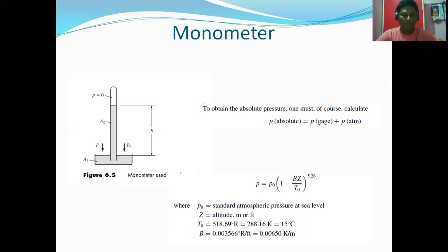So the column has a graduated scale fixed in position with the help of some instrument, set to 0 for each reading, and the level of the well will vary with the height of the mercury in the column. Okay, the 0 is accomplished with the screw adjustment which sets the level of the well at the reference position.